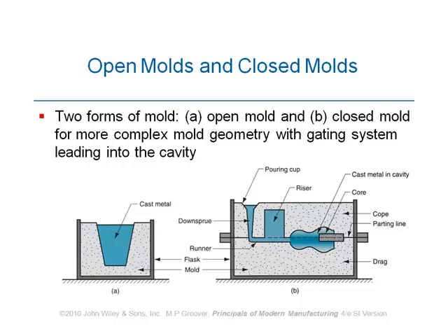So, what happens then? We've got the outside boundary, the skin, which forms the external shape of the material. Inside, we've still got molten material. After some time, inside of the material also solidifies. So what do we expect to see? Stress in the material. Well, there'll be stress in the material. We expect to see some bubbles or void spaces inside the part. Does that sound right? It happens.